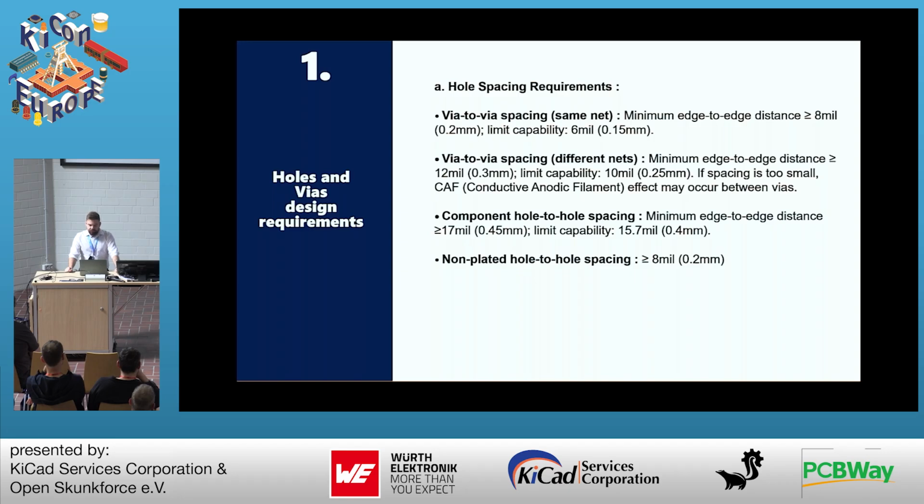And then when you have the spacing between hole to hole, component hole to hole, you have to respect 0.45 millimeter. We can try to go up to 0.4, but it's also a little bit risky, okay? And for non-plated hole, the spacing between 2 holes is 0.2 millimeter.